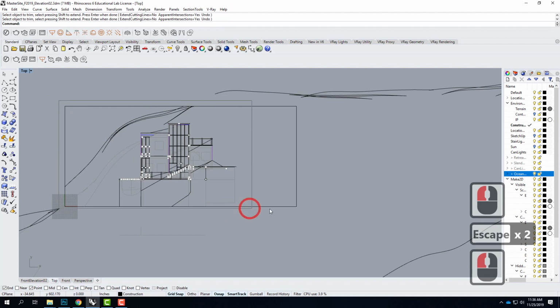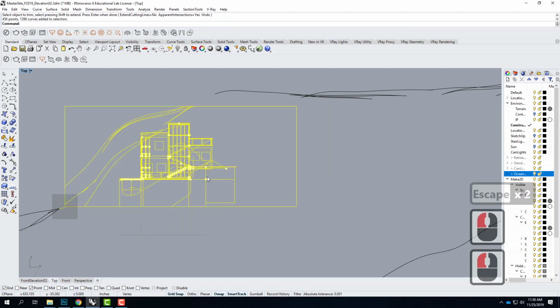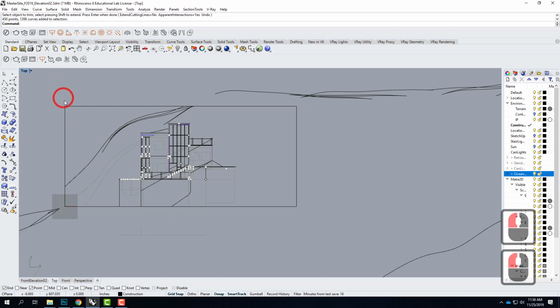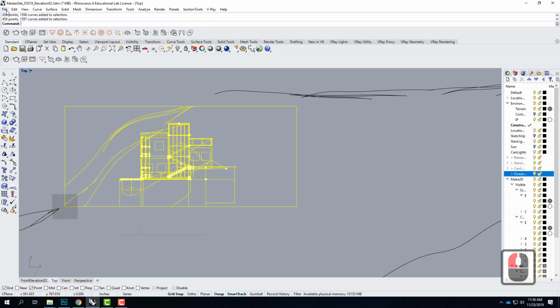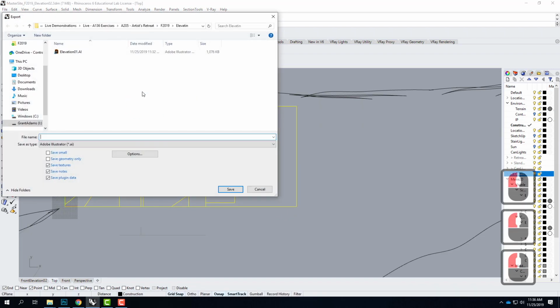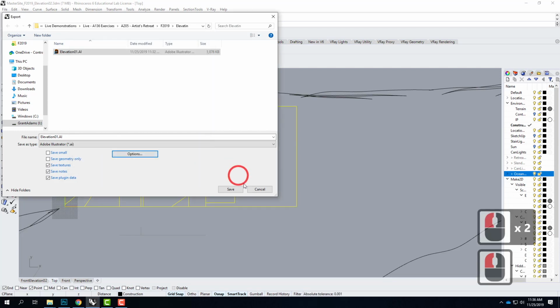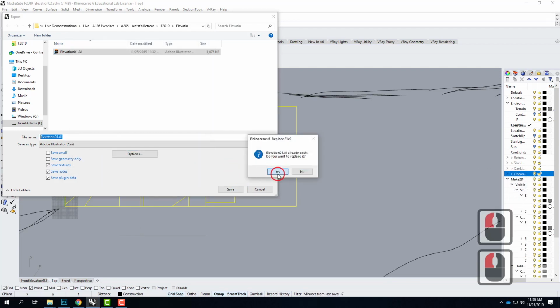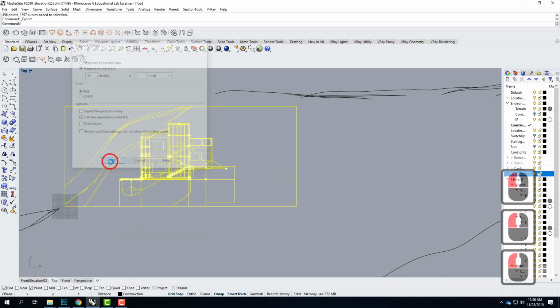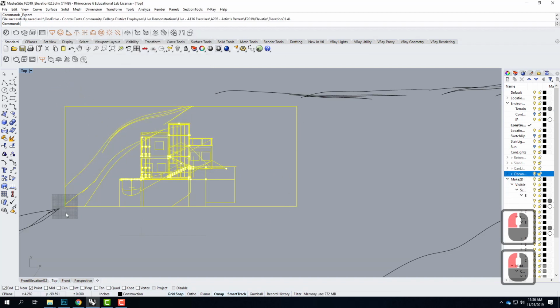Then I'll take just the bounding box here, and I'm going to export this. Oops, I don't need that little piece down at the bottom there. Perfect. I'll go to File, and then Export Selected. Under my options, still 48 to 1. I'll say OK, and then I'll go ahead and click on Save. And it'll export. It is important that this be located right at 0, 0, which in this case it was, so I don't have to move it. If it wasn't, I would need to move that viewport to 0, 0, because otherwise the export puts it in the wrong spot and Illustrator can't find it.